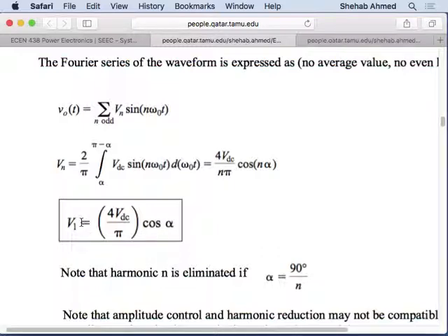All you need to do in this case to get a certain output is to raise the DC voltage at the input, because here you have control over that. So maybe if you have a transformer feeding it, increase the turns ratio, or if you have a power supply feeding it, raise the DC value of the power supply. If you can live with that, you can live with it. But what if you can't? Then people are working on modulation schemes to do that.